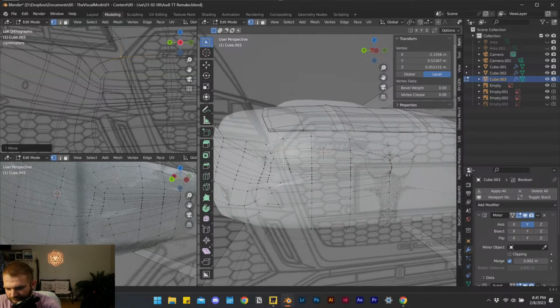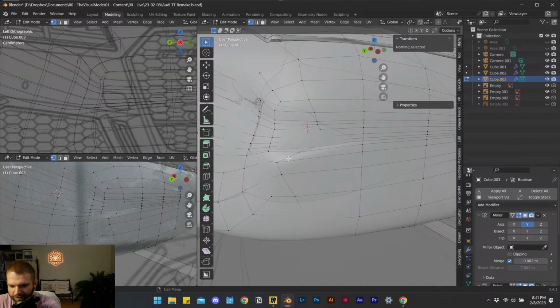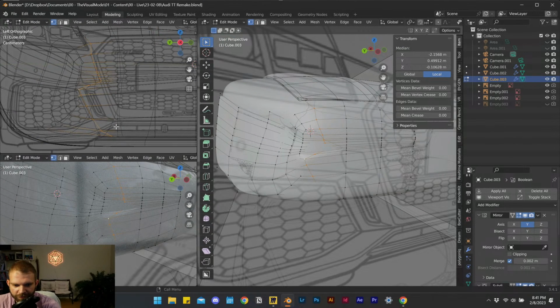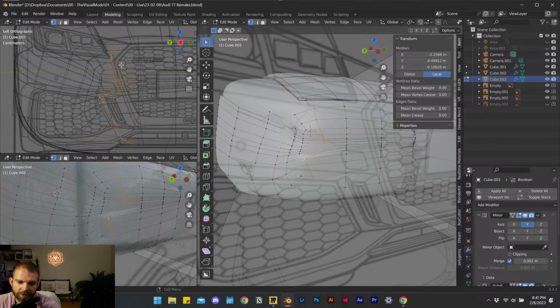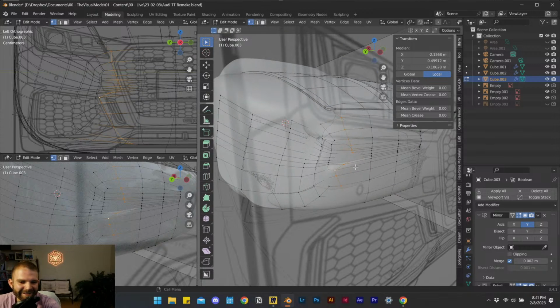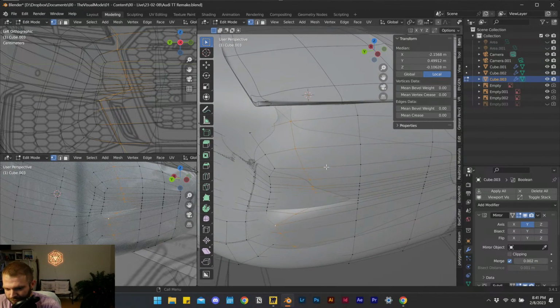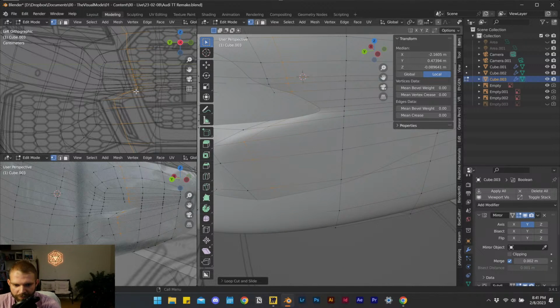All right, now that I have that edge following through, I know that this loop cut on the vehicle is essentially, as you can see here, marking out this front nose piece versus the side nose, the very side of the front. Okay. Now with that set, I'm going to hit some control loops here to start creating some thicknesses. So we see there, we can get the inside of the piece right here.